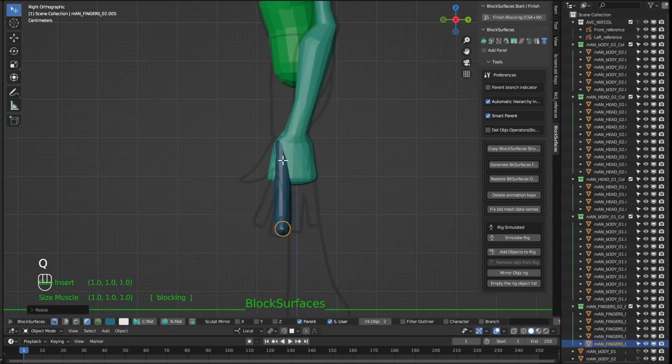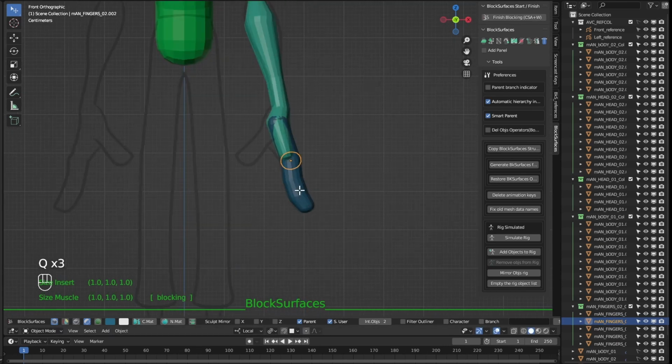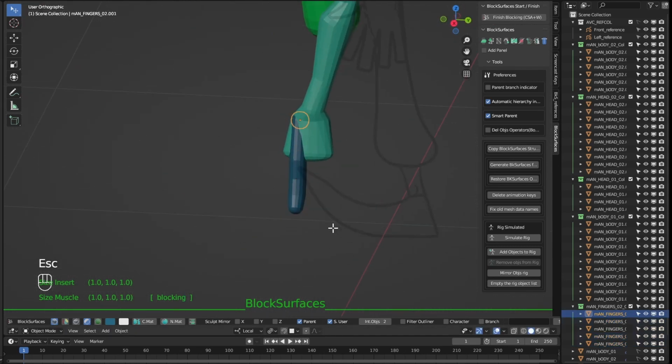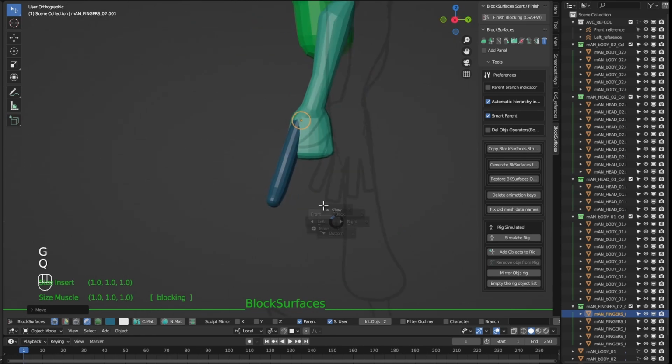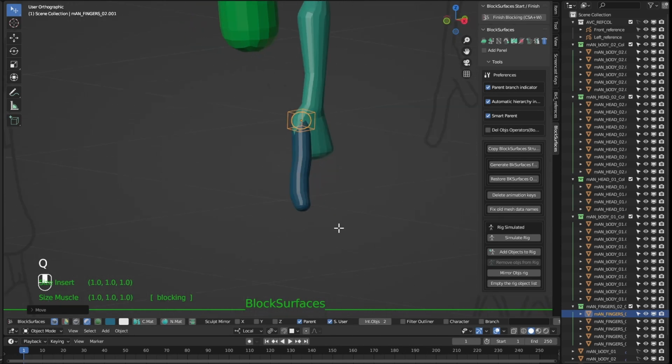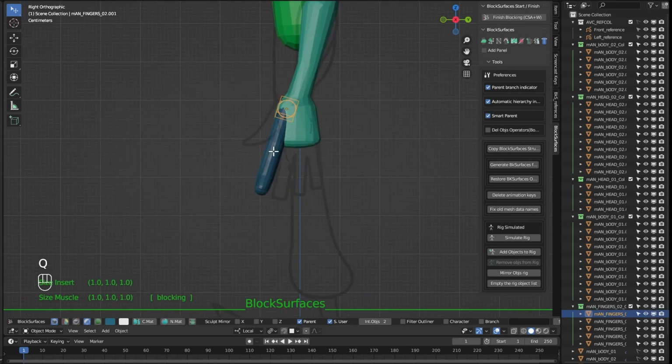And we create the objects for the finger, as they already have hierarchy we can move it. Now, we're just going to reposition it. We can use the option to view the parent object to make it easier to select this object from here. If not, it may be a little difficult for us to see it or select it. For that, we can activate this option here, and so I select it easily. When we have a branch that we want to duplicate, with the shortcut Ctrl+Alt+D, we get a new branch just like it.